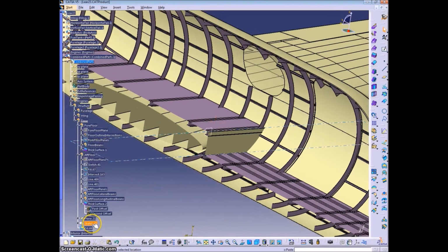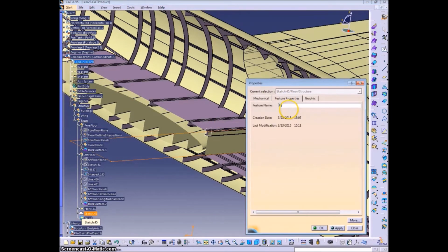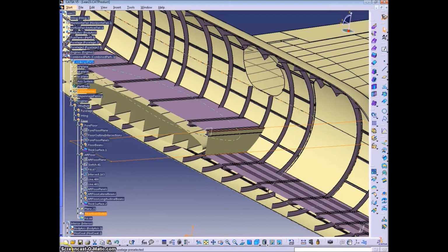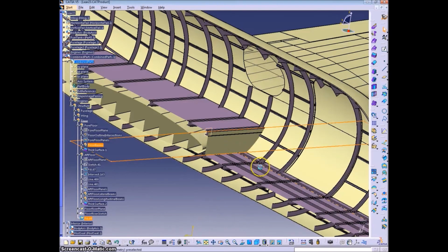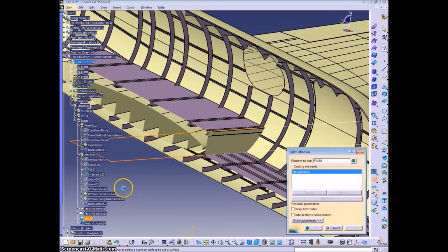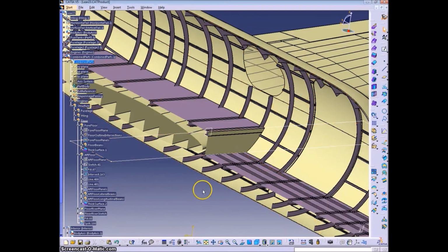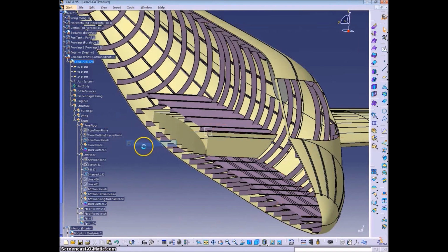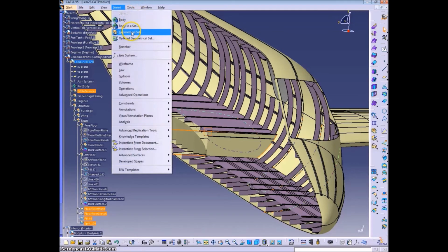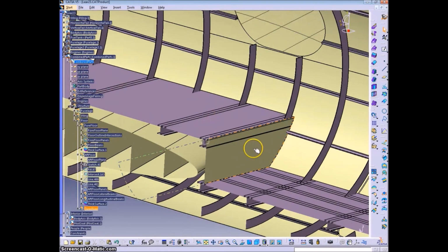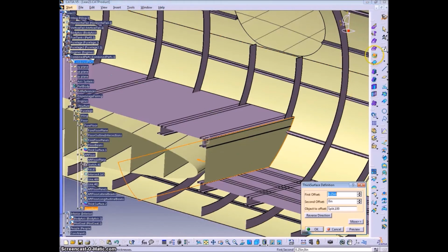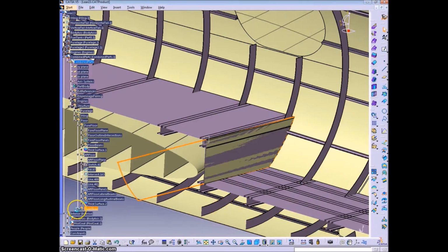Again, you can't see what's on the left side there because I have a section view on. Call that the floor riser sketch, and then the floor riser plane, and cut that with fuselage like I mentioned. Again, use the fuselage with no cutouts in it as a better practice. And then you can make this a thick surface.